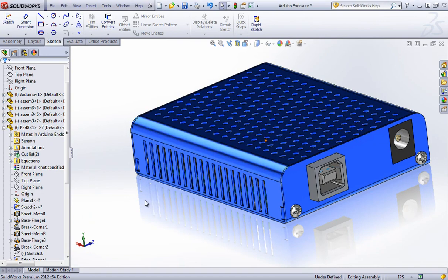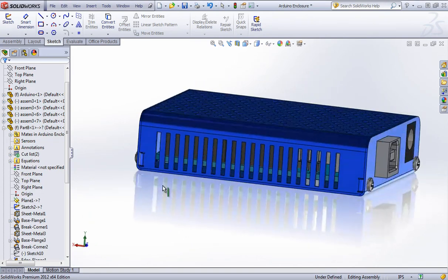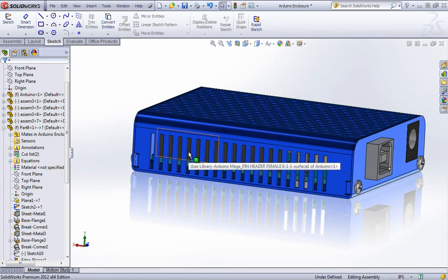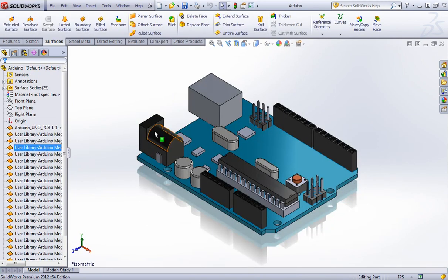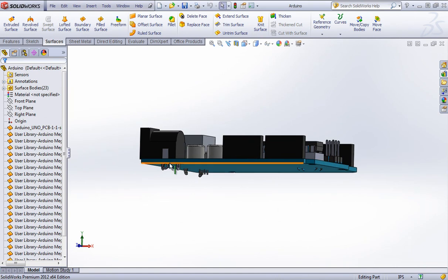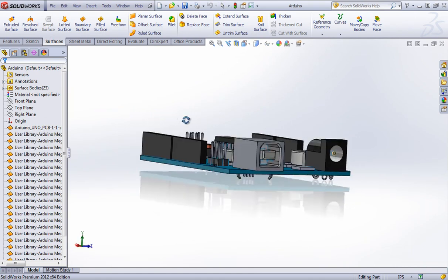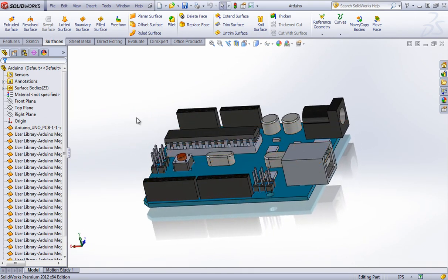So there are several ways that you can build enclosures. We could build this all in one part, similar to a master model method, like one that would be used with a surfacing model. I don't recommend that, as it's very hard to add in components after the fact, and it makes it a little bit messy to work with the individual components. And essentially what I meant by that is that in the part environment, I build everything. For sheet metal, I would not recommend this.